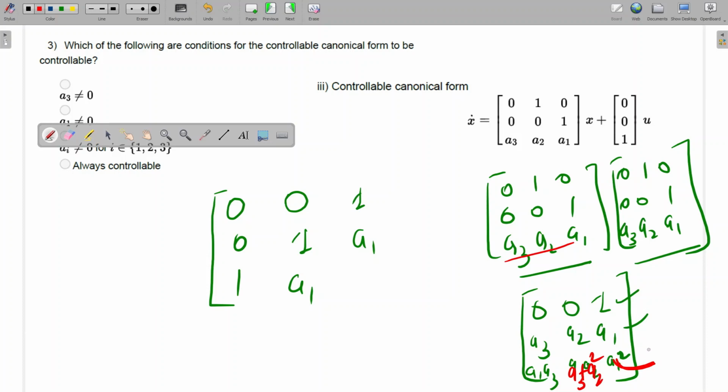column element. So this will be this into this. So middle A2 into 1. So A2 plus A1 square. Correct. So our this will be A2 plus A1 square. A2 plus A1 square. So this will be our controllability matrix for this one, QC.